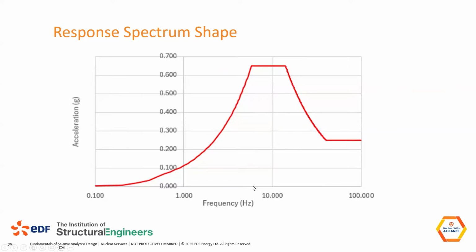So that is what a response spectrum is. I'm hoping that going through that exercise, you can better understand what it is. It's representing the response of a system to a particular input. It's the same input as the time history. It's just represented a different way, represented in terms of the response.